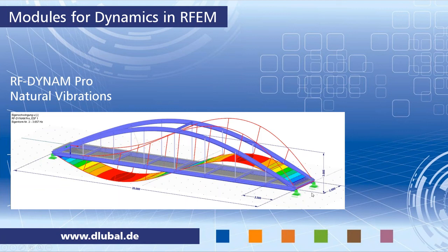which you can use to analyze frequencies and mode shapes for member surfaces and solid models. You can directly import the masses from load cases. You can combine these mass cases in mass combinations. You can also import stiffness modifications, for example, to consider the pre-stress of cables, or you can deactivate some members. You could consider the stiffness from RF-CONCRETE, and so on. So this is considered as initial conditions.